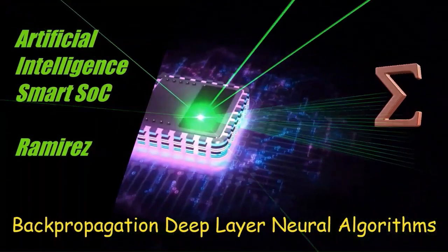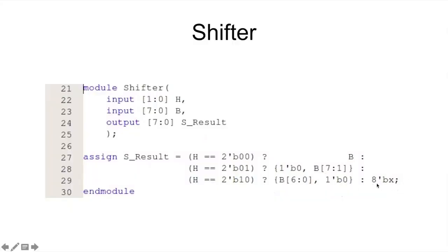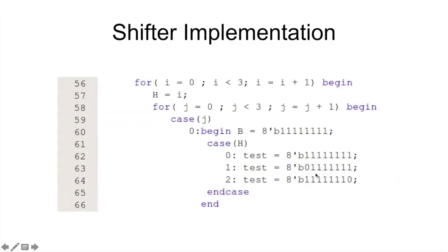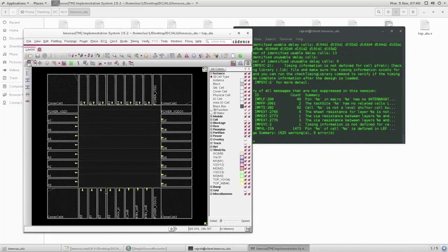This allows me to have the program route just the clock nets in the first iteration. Once it has been verified that these routes meet the clock skew objectives, the wires for these nets can be fixed during the remaining iterations.